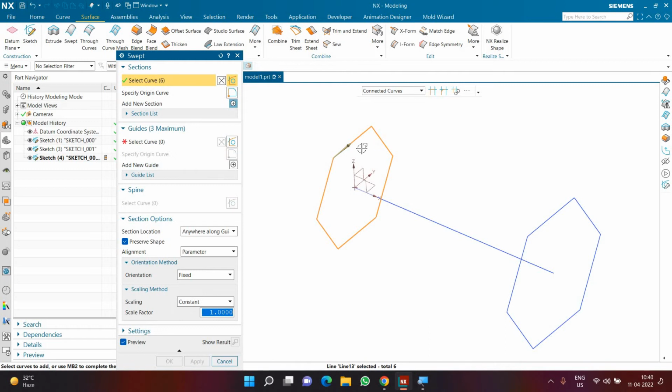Okay, I'm selecting the curve from the top line on the left side. To make it easier to understand, I'll go for a single curve selection. I'll select the top line first from the left side and then continue the selection. Technically, this is my starting curve, and this is the direction in which the selection has been done. Correct?